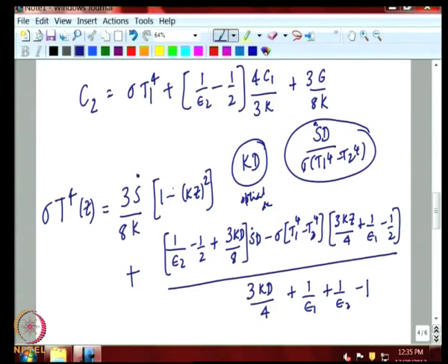So, if this term becomes more important than this term, sorry, this will be small compared to this term, and so again you have got an interesting situation where the gas temperature is essentially uniform in the bulk, except for the sharp drop near the two walls.